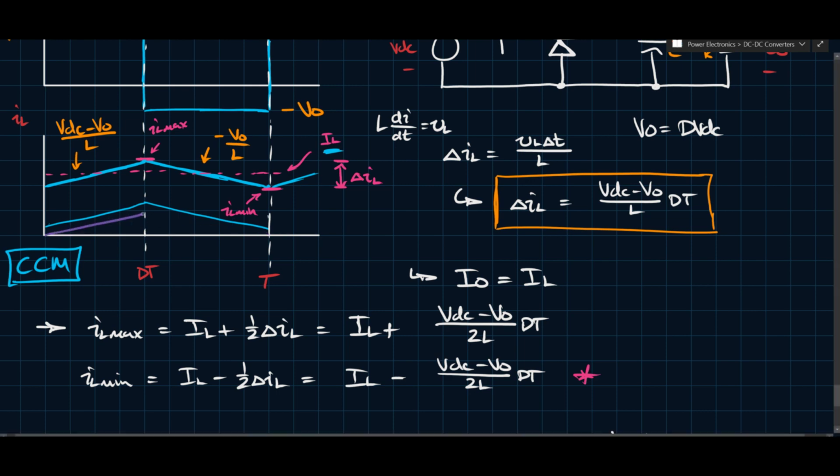Maybe it goes up and then comes down and then it stays zero, right? So the waveform that I've drawn here, this purple one, this last one that I drew, is sort of deep into discontinuous conduction mode. And the reason we know that is because there's a portion of the waveform where it's 0.